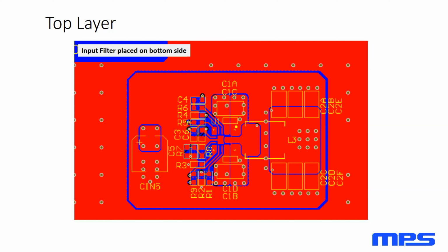Yeah, it'll definitely be it depends. So if we take a look at this particular layout, the smaller capacitor sizes generally have smaller parasitic elements involved with them, the ESR and the ESL, but they're not going to be able to store as much energy for a given case size. But those smaller parasitics help us with lower impedance to ground, in particular on the input side, just looking at this particular case. So these will perform better at higher frequencies because of that.